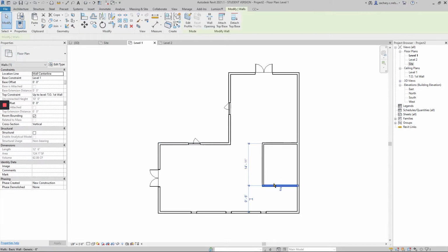So now that I've got that, maybe I want to click on this wall, and that'll bring up my dimensions between the wall here as well as this next wall over here. And let's say I want this to be maybe just a 12-foot room, so I'll just click 12, enter that in. And now I have a 12-foot bathroom, and this wall remains aligned. So the way that works is when I'm clicking on something and I want to move it, this thing will move so long as I'm editing these, rather than clicking 12, and maybe that wouldn't pull this wall in.